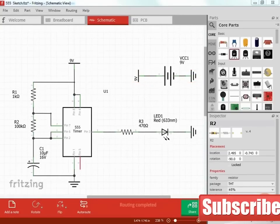We can see that everything in the circuit that's marked 9 volts, although it's not physically connected on the drawing, is electrically connected, and also with all the ground connections. We have 2 9-volt connections and 3 ground connections. This is a way that we can clean up our schematics without having lines drawing all over the place. We just put symbols for common connections, and we assume that they are all connected electrically.